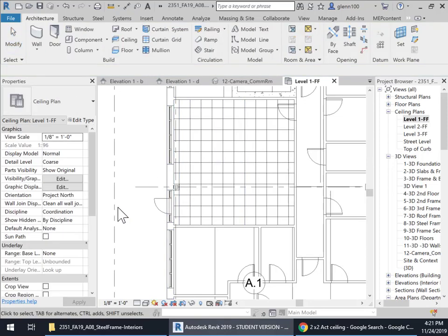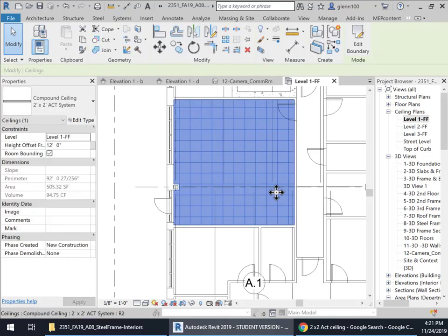The other thing is I should have checked real quick to make sure when I put this in. Let's tab here. And of course, now you'll notice that we can't see those beams and everything. There they are in gray, and it's because they're being covered up. But you'll notice that the level 1 offset was set to 12 feet, and I think I did that previously. I don't think that's the default, but we should have set that first before we did this. So in your start file, it'll probably already be set to 12 feet.